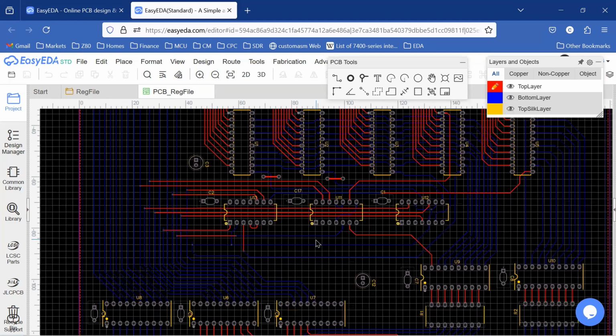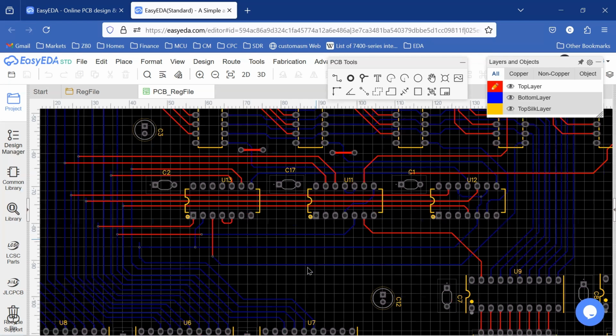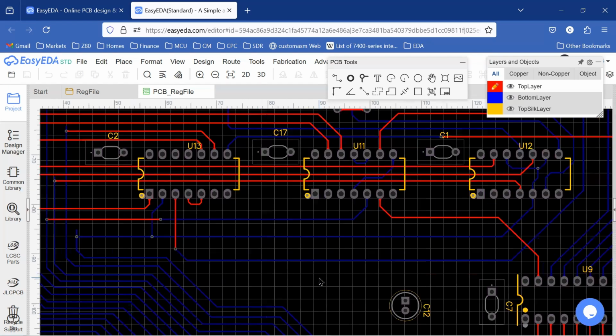And only 2 signals, I think, I had to change planes to be able to route. One of them was here. You can see this is routed on the bottom, then we have a via, and I had to go over these other lines. Same thing here. The trace starts on the top, and then a via, and then transitions to the bottom layer.